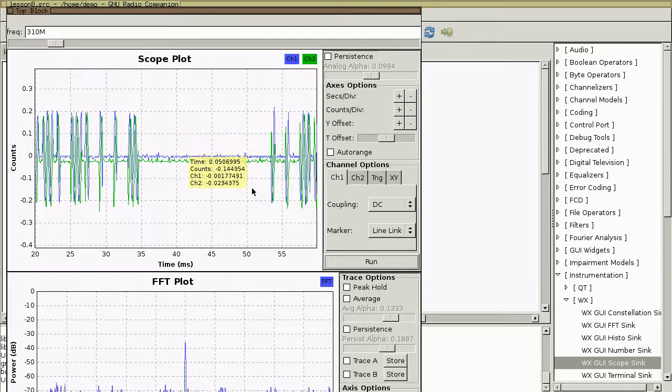You might call it a CW transmission, which is what folks call Morse code. But in this case, since it's produced digitally by a digital electronic circuit, and it's produced much faster than a human could, I would definitely call this on-off keying. It doesn't look like the frequency changes over time. When we look at the average in the FFT plot, it's very consistent and narrow, a very narrow band signal.